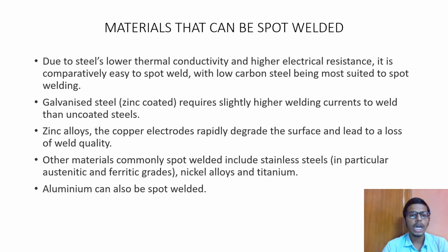For welding zinc alloys, the copper electrodes rapidly degrade the surface and lead to a loss of weld quality. While spot welding zinc coated steels, electrodes must either be frequently changed or the electrode tip surface should be dressed as they are prone to change in shape. Other materials commonly spot welded include stainless steels, nickel alloys, and titanium. Aluminium can also be spot welded.